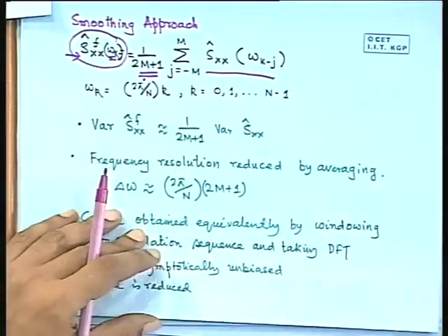What is the other approach? So here what you are doing is you are taking a data sequence, the whole periodogram you are computing. After you have computed it, from that periodogram you are doing averaging on the frequency axis. Rather than that, you can do what is known as a sort of a virtual ensemble averaging. That is, not do an actual ensemble average. See, you got a long sequence, so I will say that I will chop this sequence into smaller time sequences. So out of one long sequence, let me make 10 small sequences. Then corresponding to those 10, I can make 10 periodograms, and once I calculate 10 different periodograms, I will simply average them. That is something I can do.